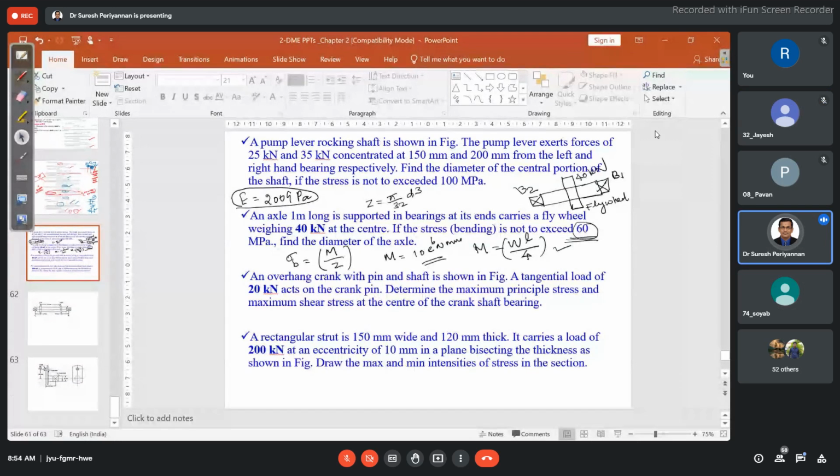So while designing the shaft, we should consider all the parameters, not only the stress under load. In the operating condition also, we should consider that the shaft should not deflect beyond this 0.36 mm. Like that, based on operating conditions also, we should consider the design criteria.